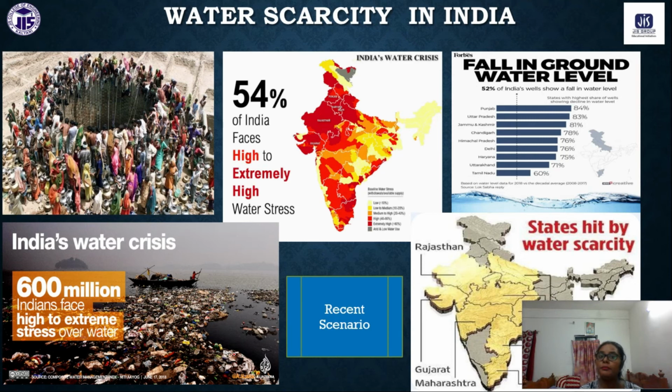And COD means, if we have both biodegradable and non-biodegradable materials, what will happen? In presence of a strong oxidizing agent, they will decompose into carbon dioxide and water. For their decomposition, whatever oxygen we require is called the COD. Now COD is always greater than the BOD, because in COD we have to decompose both materials.